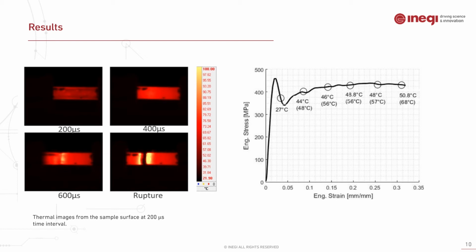You can see that from 15% strain to 50% and beyond, we are not seeing much change in temperature. Also, having in mind the thermal diffusivity of aluminum alloy and the very short duration of the impact, there's not much time for heat dissipation. So this causes a thermal softening, which could influence the plastic flow behavior of the material and possibly cause the negative strain rate sensitivity.